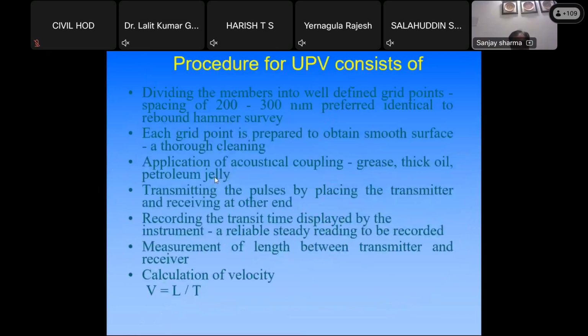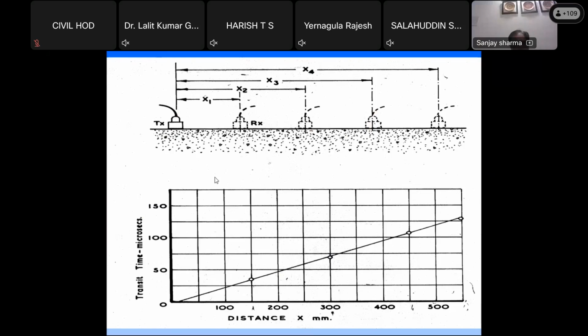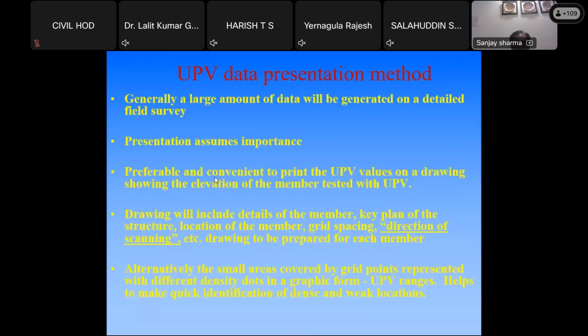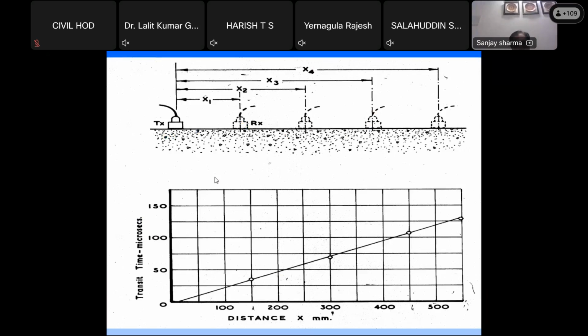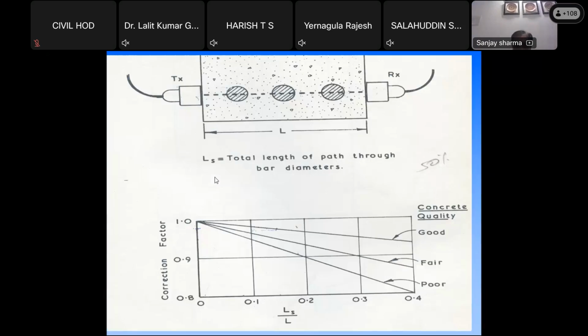And this is one of the things. So that is how you can get the concrete quality in this also. You get the data, and that data is to be properly used. For that, you can plan some sort of machine learning systems for this particular system, so this data can be more useful. However, for our purposes nowadays we are using this data only for getting the concrete quality, and correlating it with the rebound hammer, using both things together.